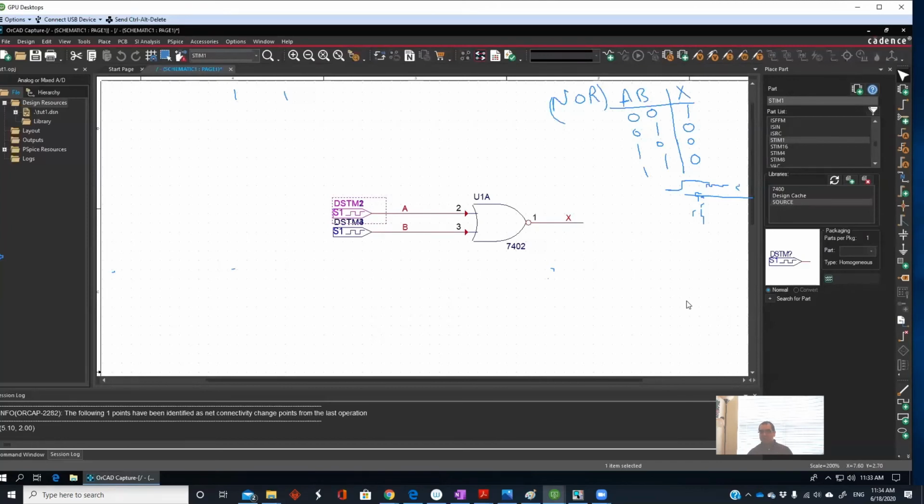So the voltage marker, we can find it here. This here is the voltage level marker. Just add one at each line, one here, and another one here at line B, and another one at X. So that will allow you to see the waveform generated by A and B, which you already set up, and observe the output X.